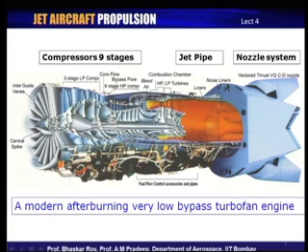And then of course, you have the basic core flow coming through the next 6 stages of compressor, goes into the combustion chamber and goes into the turbines. Now, that we have compressors in 2 groups, or what we will be calling more and more as 2 spools, you would need to have turbines also in 2 spools.